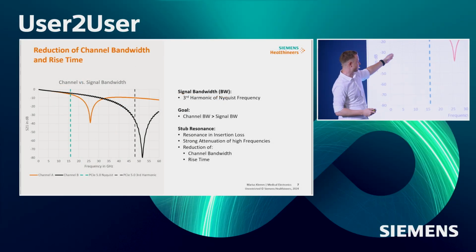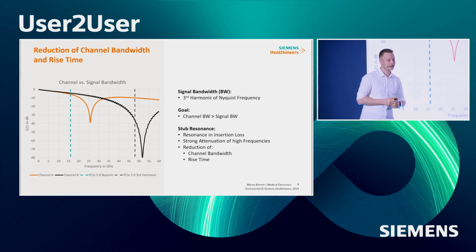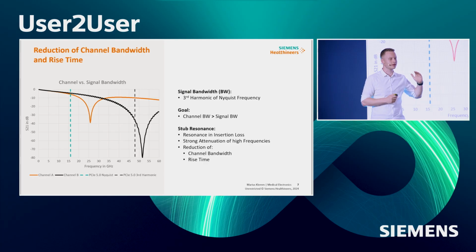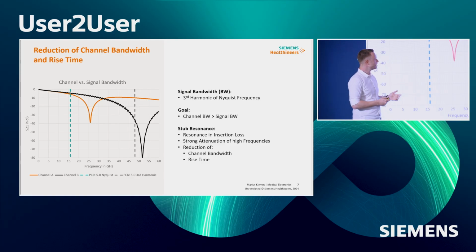And if we have these drops in the middle, for example, that I'm going to explain in a minute, then it's like a power suck out, where the power is attenuated extremely strongly. And so these frequencies will be blocked. They will reduce our rise time in the digital time frame, and this will make the digital signal flatter. This is what we saw in the last frame.